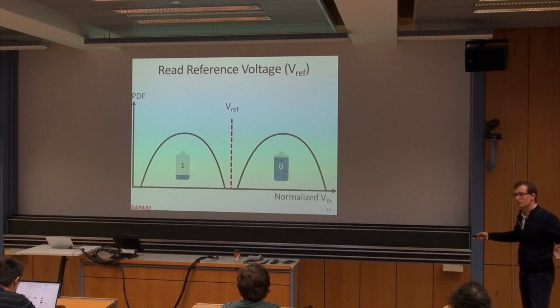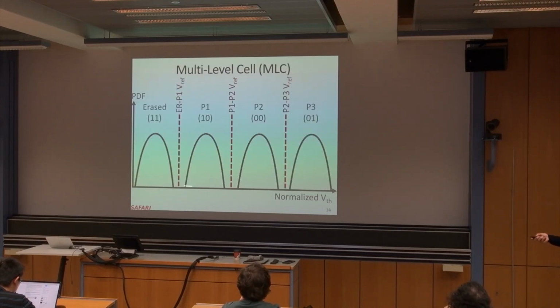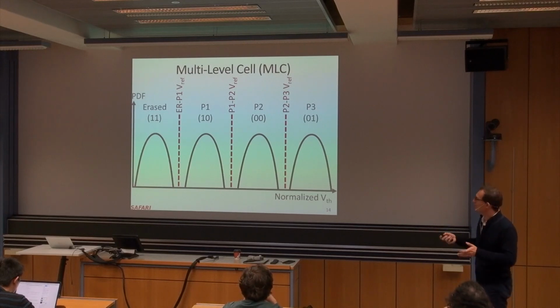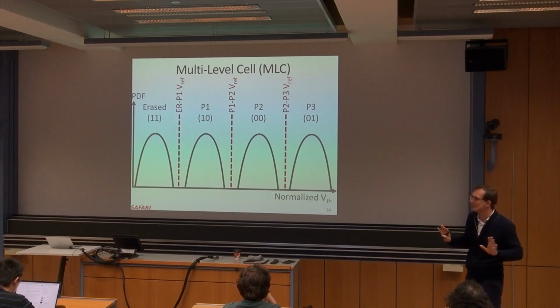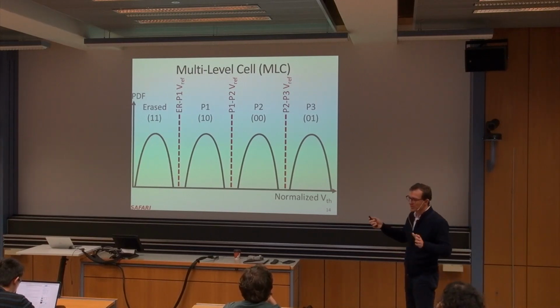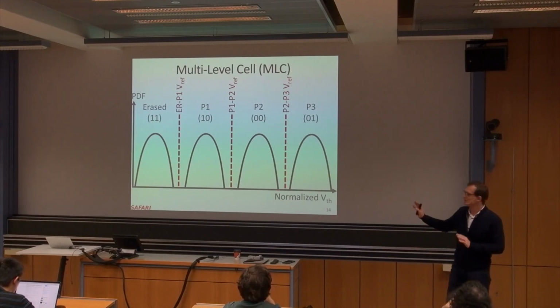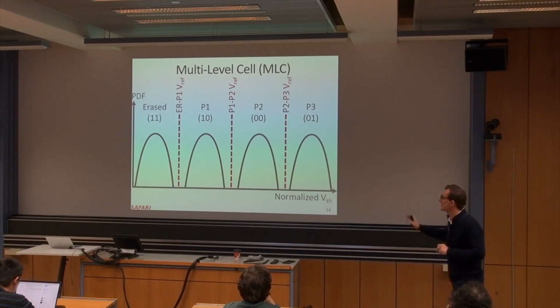But if you want to go to multi-level cell, as we've discussed with PCM, it's relatively similar. You chop up the threshold voltage range into 4 in this case. And now you have different states. You have an erase state. It's usually called an erase state because this state is actually not programmed, right? You erase the block, and if you don't want to change the value from that, you don't touch it. You don't program that cell. Actually, it usually has negative voltage because you don't touch it. You raise it to 0, and over time it drifts to negative. As a result, we're not going to show it. We're not going to be able to even measure it in a lot of distributions in real life.